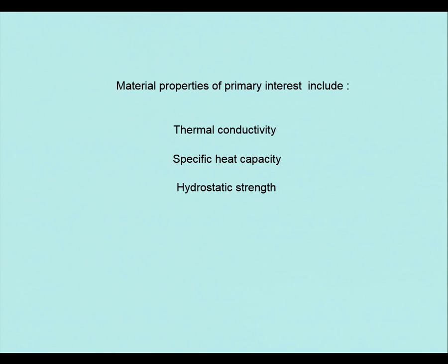But thermal insulation coatings can range from very cheap, which are no good, to very, very expensive. But the one thing the thermal insulation's got to do, when you put it down in considerable water depths, is cope with compression: the more you compress it, the higher its density gets, the more it conducts heat. But the other thing is the higher the temperature, the softer it gets. So the softer it gets, the more it squashes. And then they're all subject to absorbing water. It's an absolute veritable nightmare. So that's why we often do pipe in pipe.